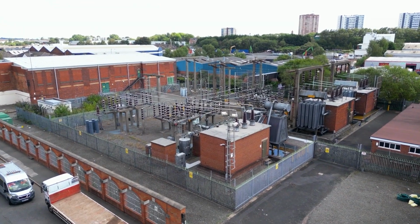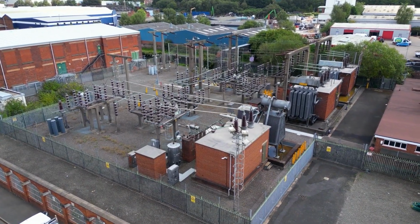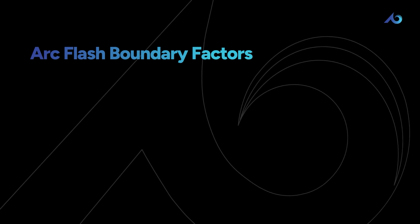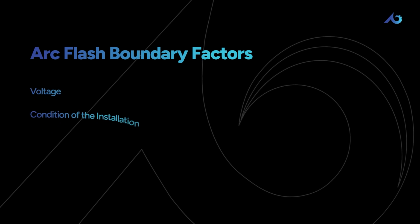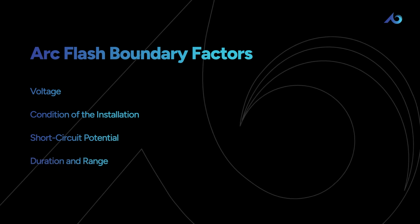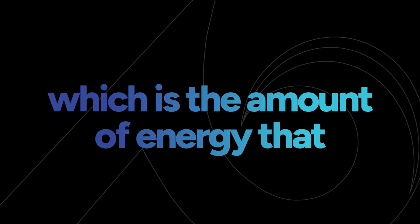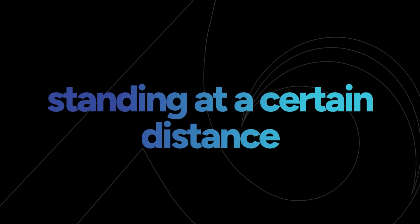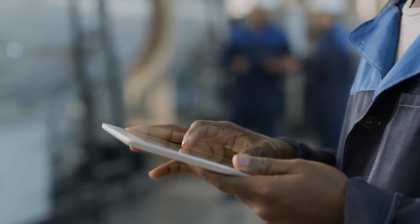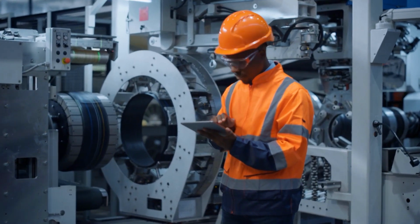But anyone working within this boundary definitely needs to be wearing arc-rated gear in order to protect themselves from far worse. So to determine the arc flash boundary, a qualified person needs to look at multiple factors, like the voltage, the condition of the installation, its short circuit potential, and the duration and range of a potential arc flash. This process includes determining what we call available incident energy, which is the amount of energy that could potentially reach a person standing at a certain distance from the arc flash. That qualified person can refer to Annex D of the NFPA 70E, which is where you could find different calculation methods for setting the exact distance of the arc flash boundary.